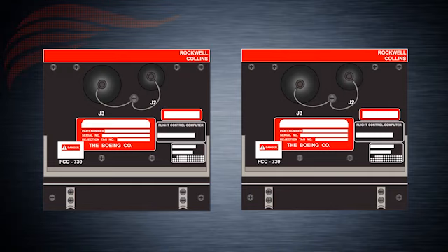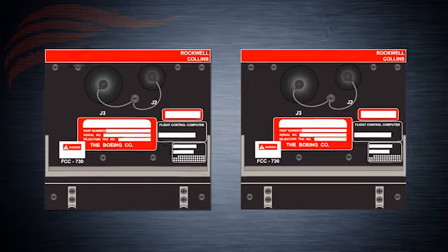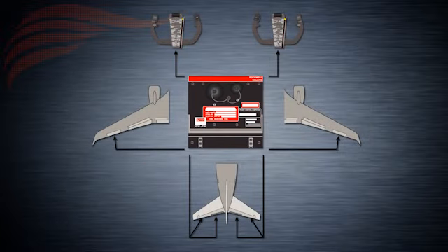There are two FCCs located on the 737 NGX. These are referred to as an A and B FCC. Each FCC has its own set of 16-bit processors. Each processor calculates different functions of aircraft operation. This is a visual representation of what components interact with the FCC, which also lays out most of the components of autoflight, since all components interact with the FCCs.